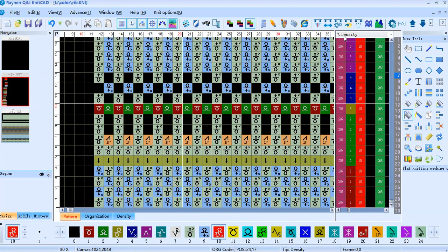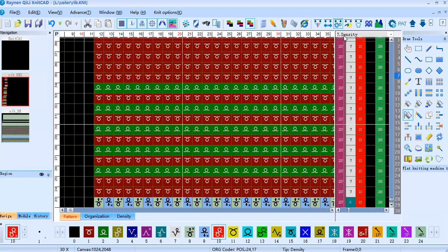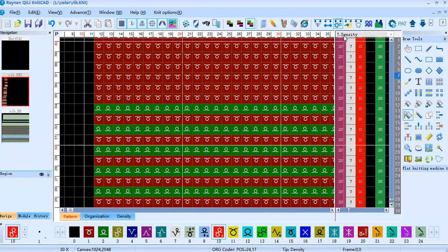Do you have a specific number for knitting density? A specific color? I mean, should you use color 1 or 2 or 3 or 4? If you never touch the knitting, you can follow me: locking use 1, jersey use 2, starting rib use 3, tube use 4, rib use 5, the rib last row use 6, body use 7, transferring use 10. You can write it down and remember it.